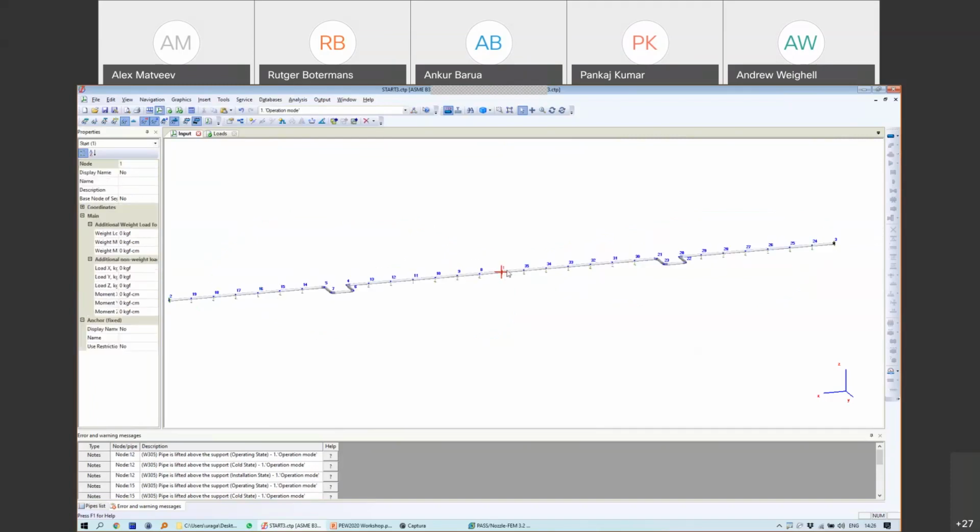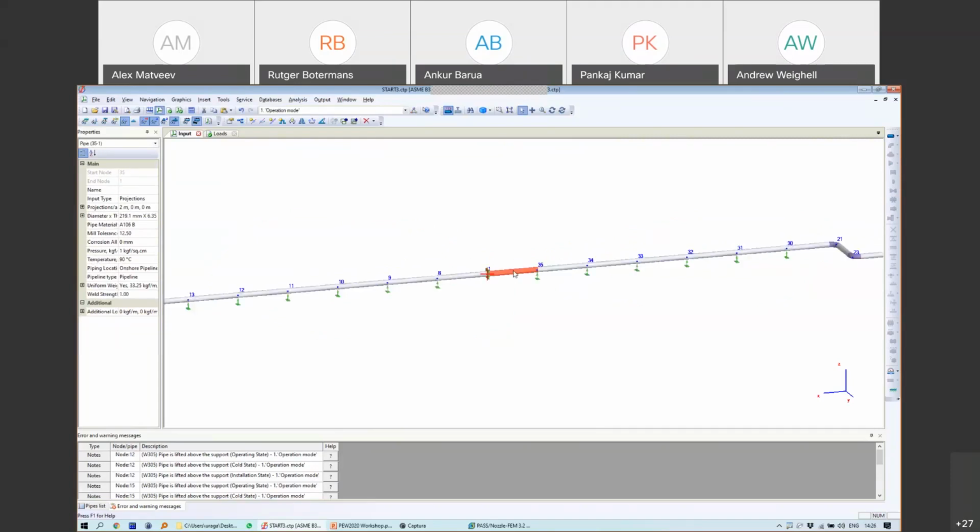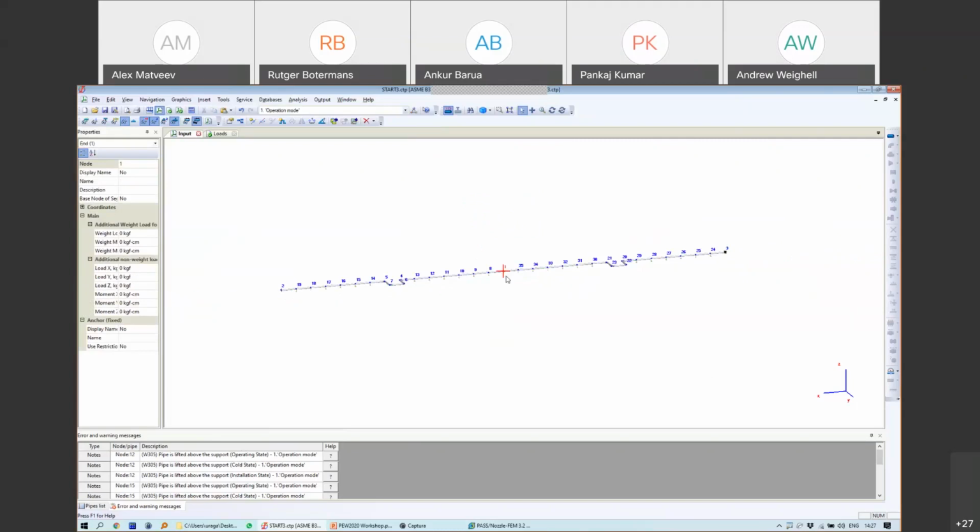Of course you can check all the situations, change the temperatures, change the friction factors, and change everything in this model, but it will take a lot of your time. So this trick with the factor 0.8 is much easier to use for approximate solution during the piping design. So, as I said, it's widely used by Russian companies.